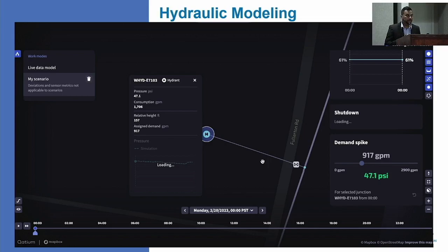Now let's say you have a little bit of an idea about the hydraulic model, there are certain rules in the model about when the pump is normally open, when the pump is normally closed. Not every person in the system knows when a pump is normally closed or normally open. So what we do is, because we're getting the real-time SCADA data into the system, this information is fed in real time. Every 15 minutes data is fed into the system. Now, instead of all the field guys or all the operation guys knowing it first, the model knows that this pump is normally open or this pump is normally closed. And that's how it keeps on updating.